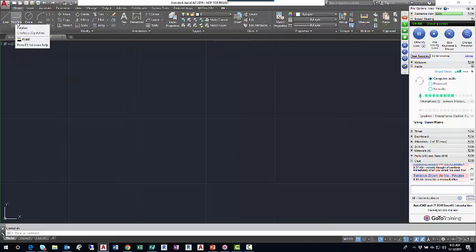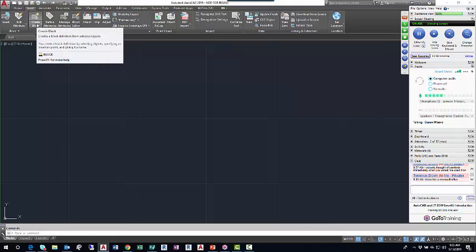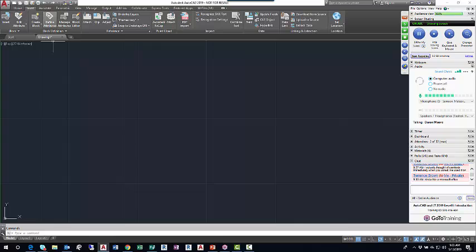However, there are other tabs on the ribbon. If I switch to the Insert tab, this tab is designed to allow me to insert any available file format into an AutoCAD drawing. Again, it's saving us the extra work of creating new line work. You can insert one drawing into another. You can convert line work into sort of block drawings, add text to your drawings and so forth. You can actually import PDFs. So the Insert tab allows for the easy insertion of other file types into your current drawing.